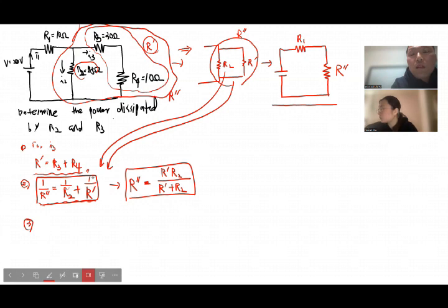So you can think of this DC circuit with only two resistors. One is given in the current path of I1, and the other is the effective resistor out of R3, R2, R4, which is R double prime. They are actually connected in series too. So you can think of the whole total equivalent resistance as R triple prime.